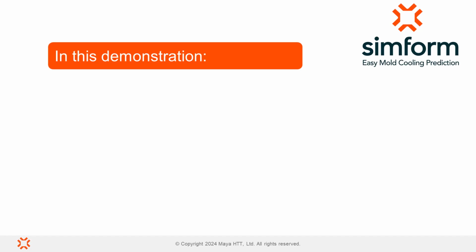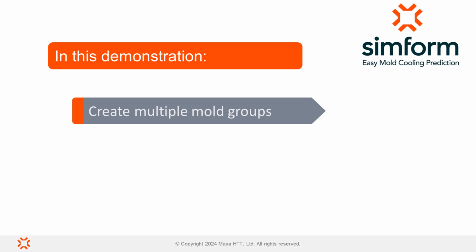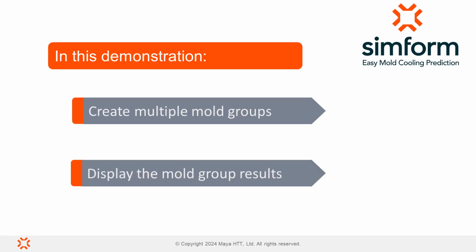In this step-by-step demo, we will show you how to create multiple mold groups to define mold components and inserts with different materials, and how to display the mold group results.